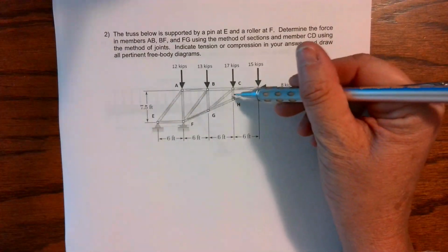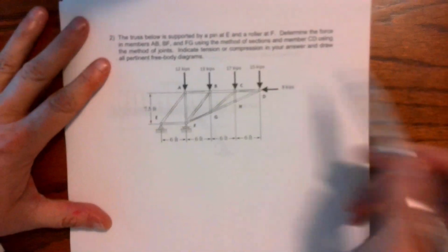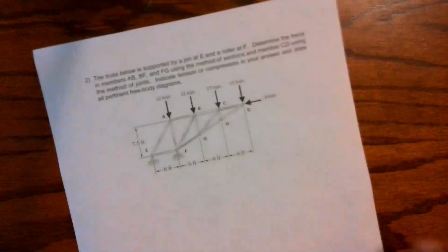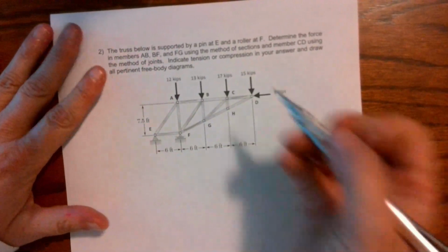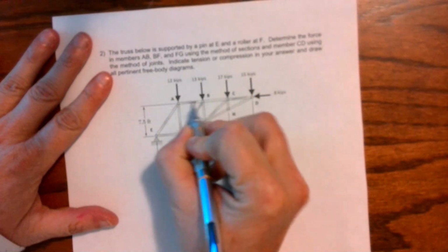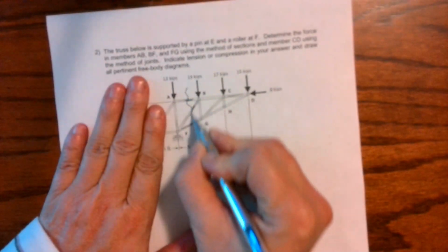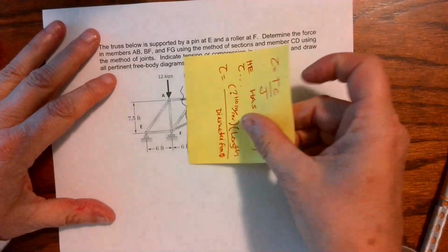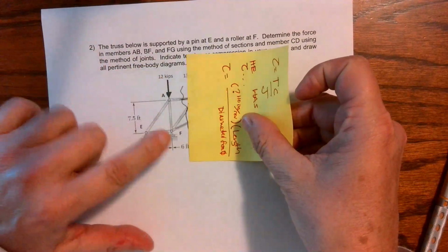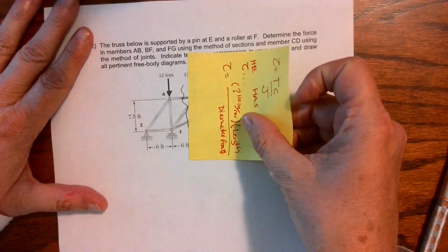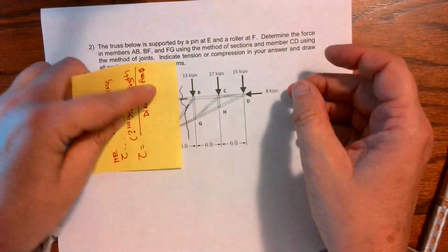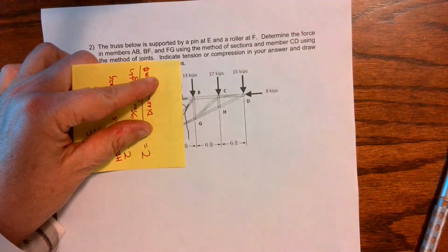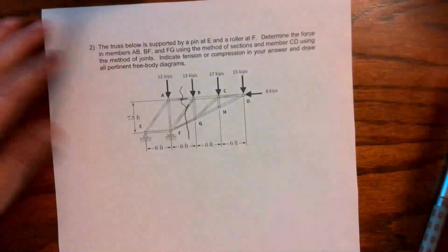And so, if we're looking at this, like we talked about in class the other day, if you have a cantilevered truss, you don't even have to find the reactions, okay? And what I'm noticing that I want is AB, BF, and FG. So if I cut right through here and look over here at the left, I would have one force, but I'd also have to find my reaction at the roller and my reaction at the pin, because I'd have to include all of this. If I look at this side, I do have a lot of applied forces, but I don't have to find any reactions, so it saves me a lot of time.